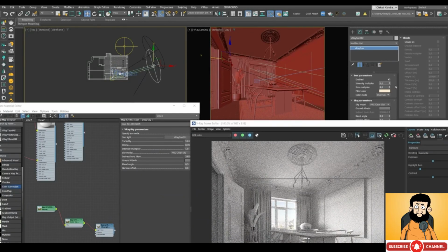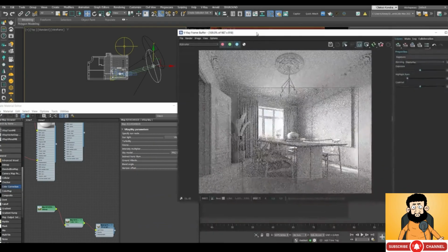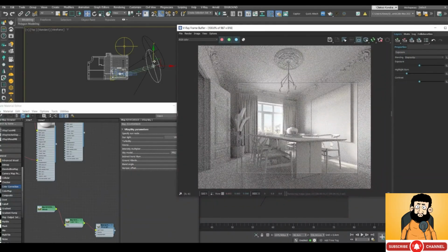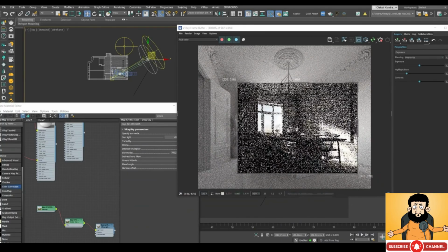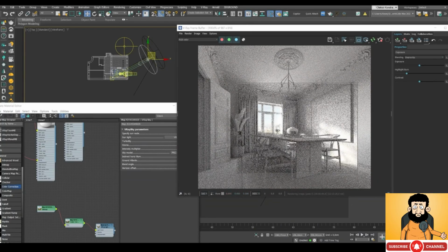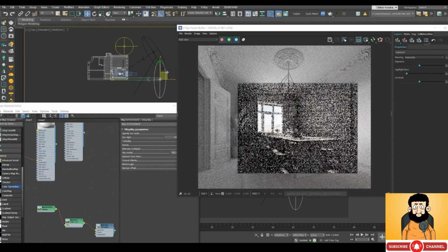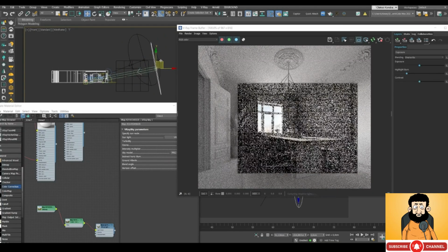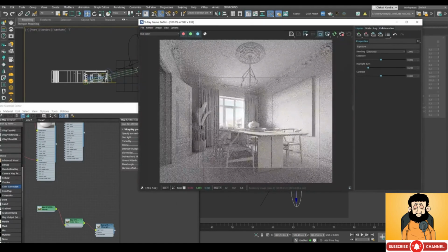It's now activated, and also I'm gonna increase the intensity value to show you how it works. See? There's sunlight on the floor now. I can direct it like this, for example, or I can direct it deeper into the room. So I regulate the sun pattern with another sun, basically. So I don't have to work with the sky and the fill light.